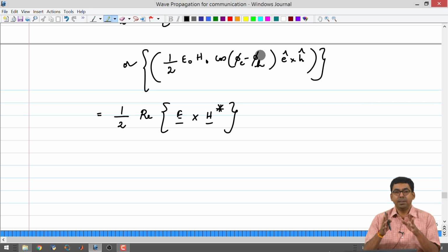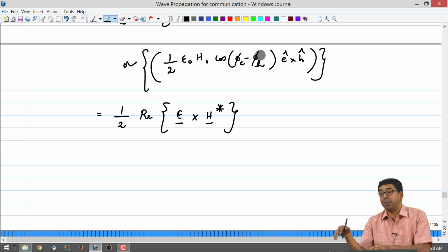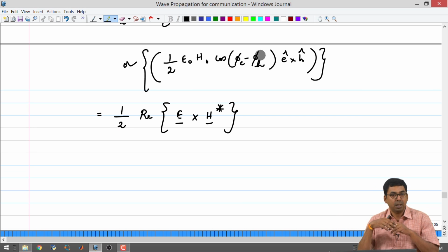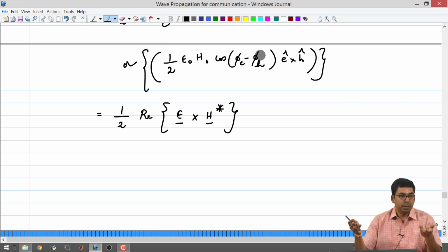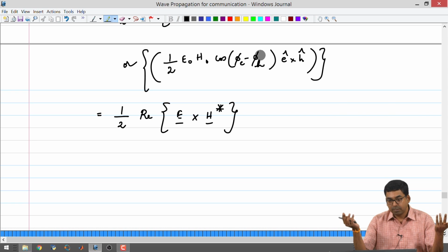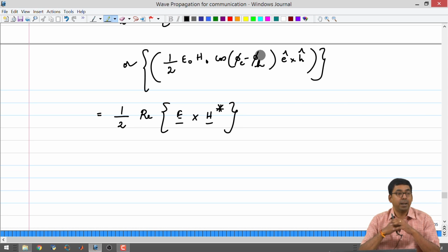In a resistor, we say that the current and the voltage are in phase and the power will simply be V times I. If you want to be very specific, you can say V times I cos phi, where cos phi is your power factor, and phi is the phase difference between your current and voltage. Because phi is equal to 0 degrees, cos phi is 1 and you get VI watts.